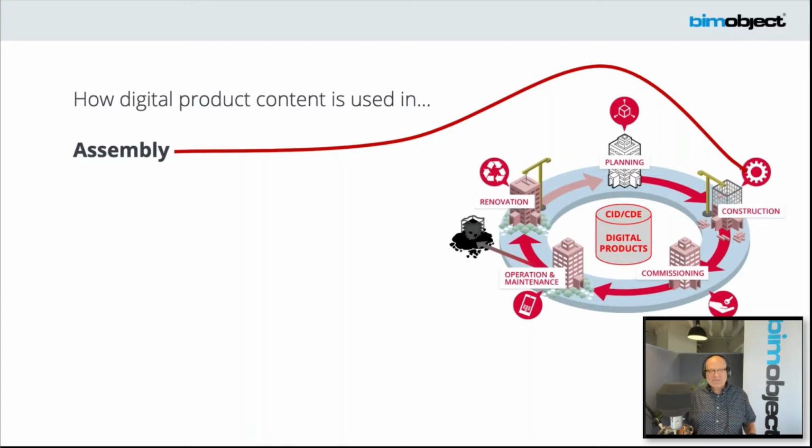It's used a lot of places for this, but that includes a lot of different aspects. One of them is site logistics. How are they going to assemble this on the site? If it is being brought in as prefabricated components, what's the logistics? What's the sequencing? Material sequencing and handling.